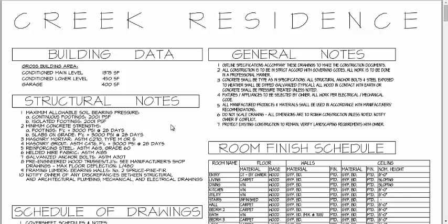So if you think about a square foot, basically the size of most people's shoes, you look at that size and you say, okay, if I went down to the footing, I ought to be able to place 2,000 pounds on that size, 1 foot by 1 foot of footing, and not ruin or crush the footing and not sink into the earth. So a lot of weight. I mean, that's almost a small car that you could put on top of that. 2,000 pounds is 1 ton. So 1 ton of weight in that particular spot. The isolated footings are the same thing.